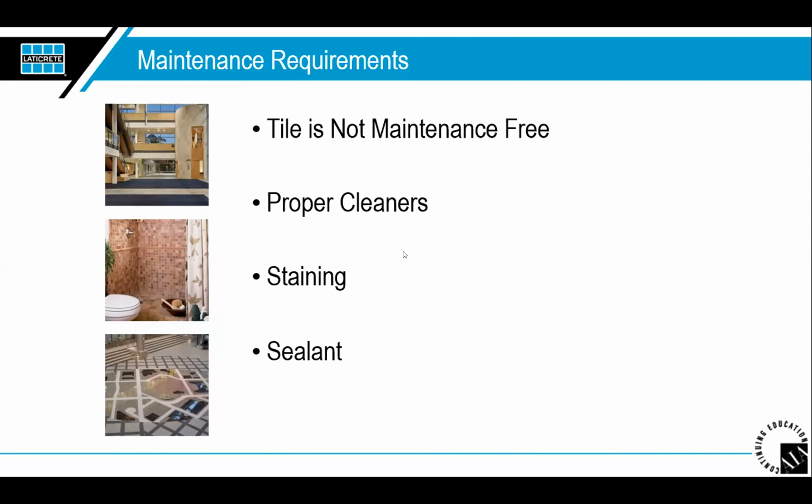I can't be quoted on this, but I want to say there might be some rapid curing urethanes out there. But with an epoxy job, 24 hours later that job is going to be rock hard, and the installation behind it at 28 days cure is going to be around 3,500 psi. So highly stain resistant, and it's going to get very, very hard as well. And again, there's the sealant as well. The silicone we're talking about needs to be checked on a regular basis for wear and decomposition due to chemical cleaners. If you see that being an issue, it needs to be cut out and reapplied.